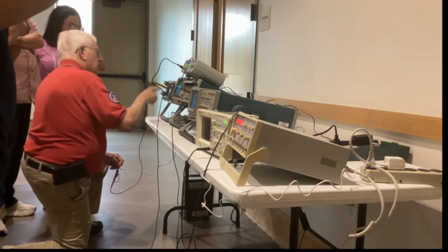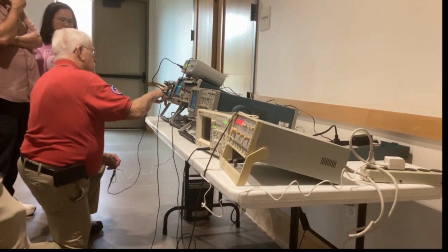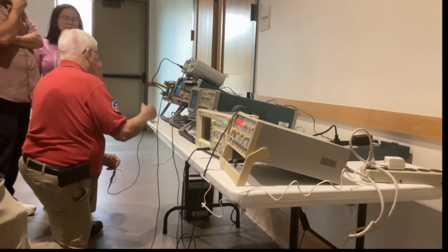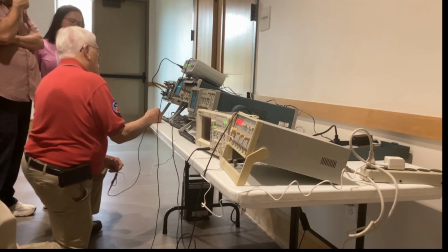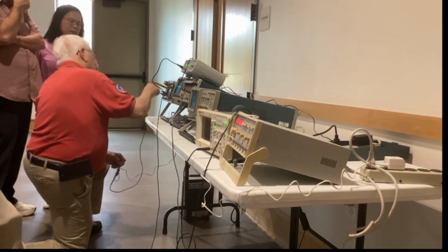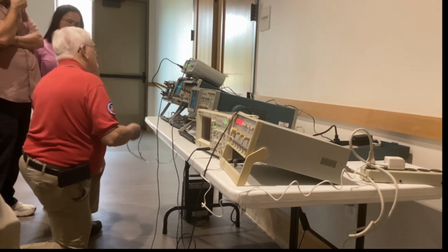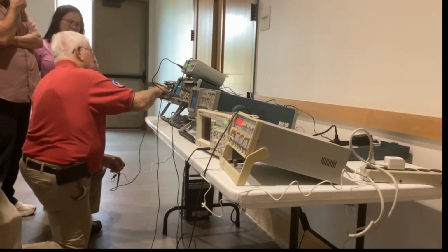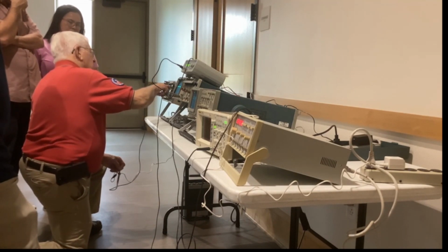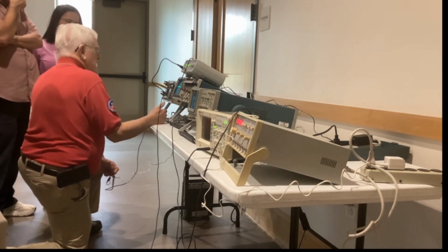In this case, I have to read it, though. I'm doing 5 milliseconds per division, so I've got 25 milliseconds. We calculate that out; it should come out right at 60 hertz. And then voltage-wise, we have to do this manually. Check the probe: I'm on ×1, so it's not attenuating. We're doing 2 volts per division, so we've got 2, 4, 6, 8, about 9 volts coming out of that with no load on it. So that's kind of the idea behind it.